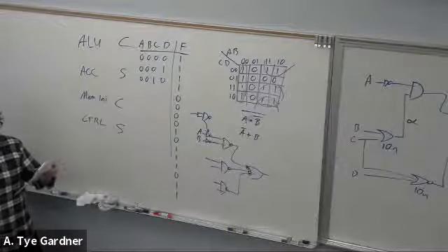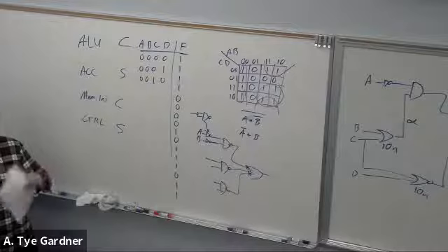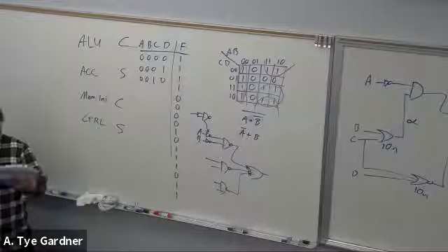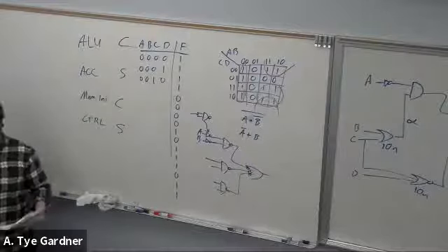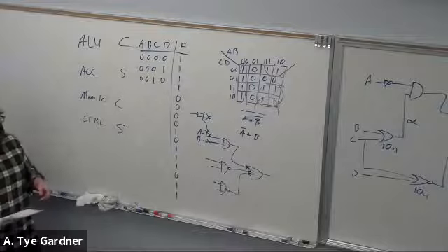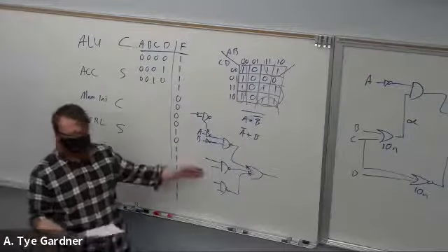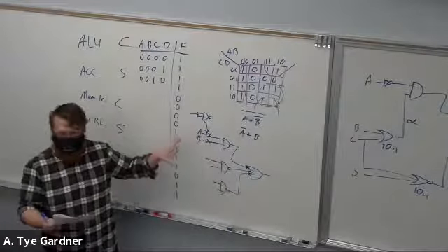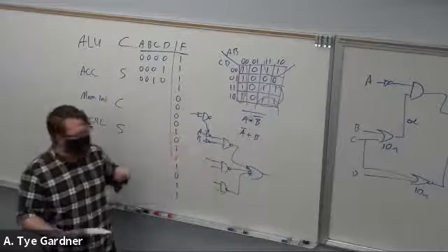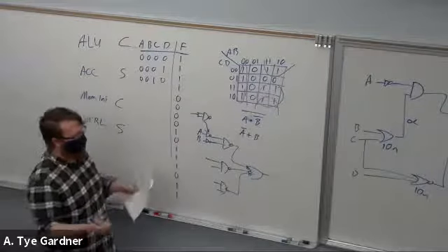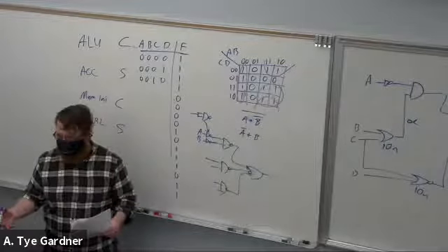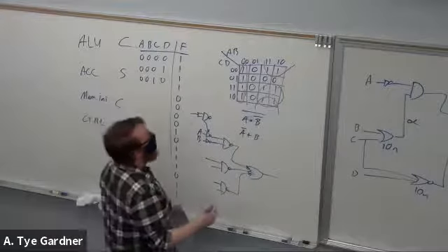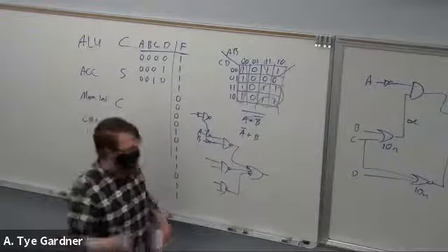Then I ask, write a combinational VHDL expression for this circuit. There's 2 different ways to do this that are okay. One of them is the NAND gate circuit, and one of them is the AND and OR gate circuit. I didn't specify which circuit when I asked for it, so either one would be correct. If you were to do that, combinational VHDL means no process, right? It's just an assignment statement.